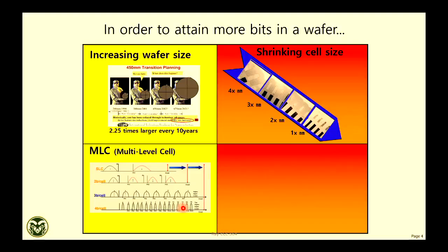And that's why QLC, even though it is not reliable, even though it is a little bit slower, right? Or even though it has less lifetime, endurance being another important quantity for non-volatile memory. Everything is poor for QLC. The only good thing is less cost because it is highly dense. You pay cost per bit, right? So in cost per bit, QLC wins, and that's why this is the most popular technology right now.